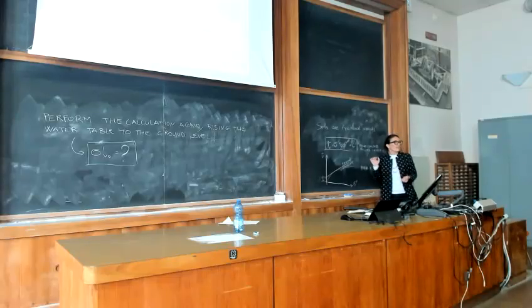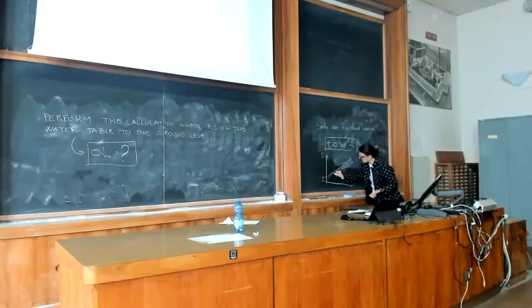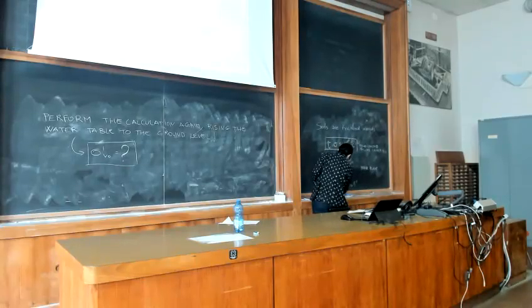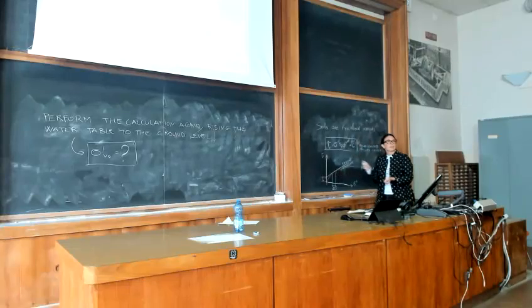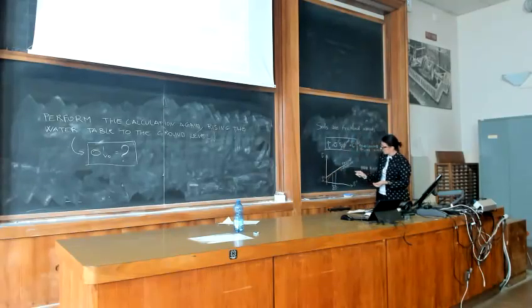What happens when we define a line for soil? When we define the line for soil, it is because we are testing our soil for a particular interval of stresses, from here to here, and in this part of the real envelope we can find an approximation of this behavior, which is a line, with a specific inclination phi and an intercept c.